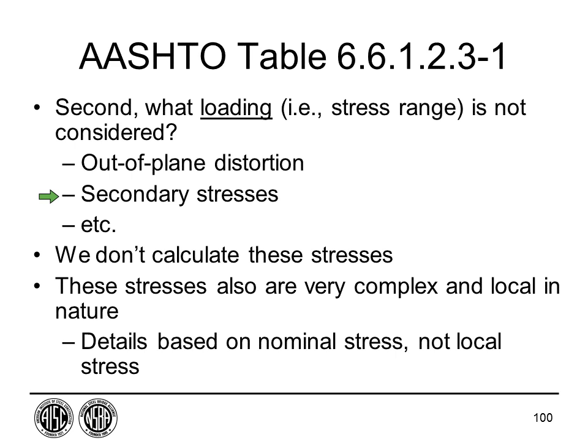But then we put them together and hope everybody plays nicely. And sometimes that isn't the case, that there are these secondary three-dimensional stress ranges that occur. We don't calculate those, and so those kinds of stress ranges are not what's considered in the table. They're very difficult to calculate, they're complex, and generally we've come up with details that aren't susceptible to this. So today this usually isn't an issue. But it's primary stresses that we calculate. That's what we worry about.